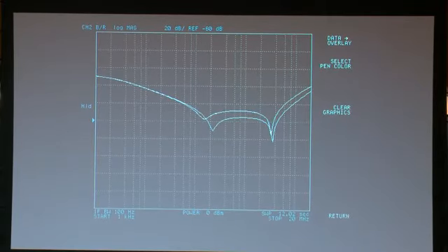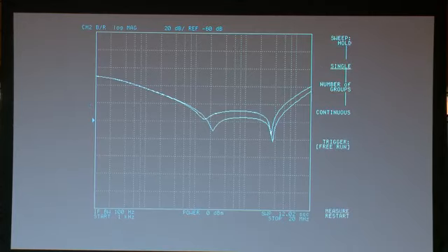The next one, we have a bad layout with parasitic inductance in series with the capacitor, but we fixed the problem with the inductor, right? So we're fixing one at a time. And I should say, by the way, that notice we don't have a ground plane set up, we don't have all this other stuff, so this test setup wouldn't qualify for getting repeatable results in all kinds of systems.